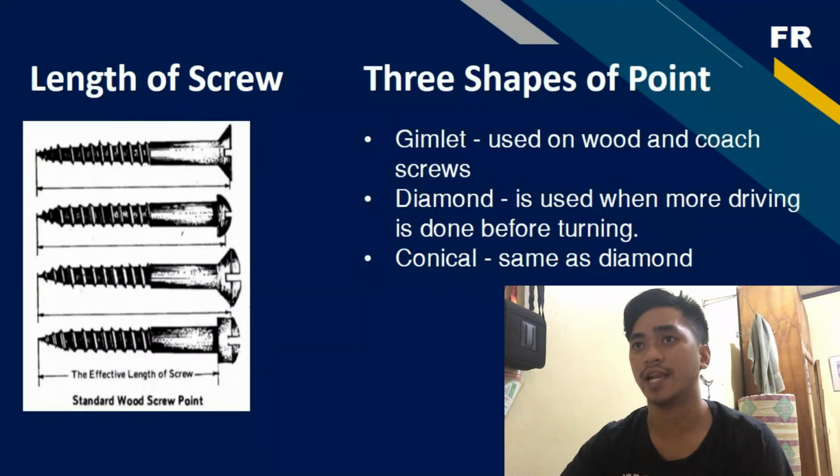Now for the length of screws. Length is measured from the point at which the head sits flat with the surface to the tip of the threads. Hex, pan, truss, button, socket cap, and round head screws are measured from right under the head to the end of the threads.